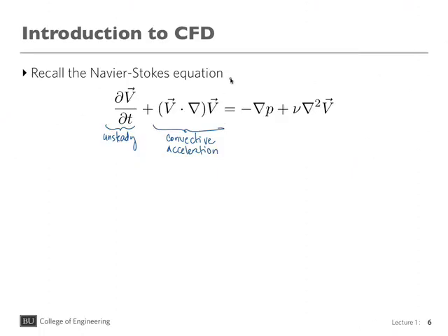And the convective acceleration really represents, so the velocity is a vector field, right? And as a field, it has a different value in space. So the acceleration has these two components, because one component represents how the velocity of an element of fluid changes with respect to time, for whatever reason, forces and everything.